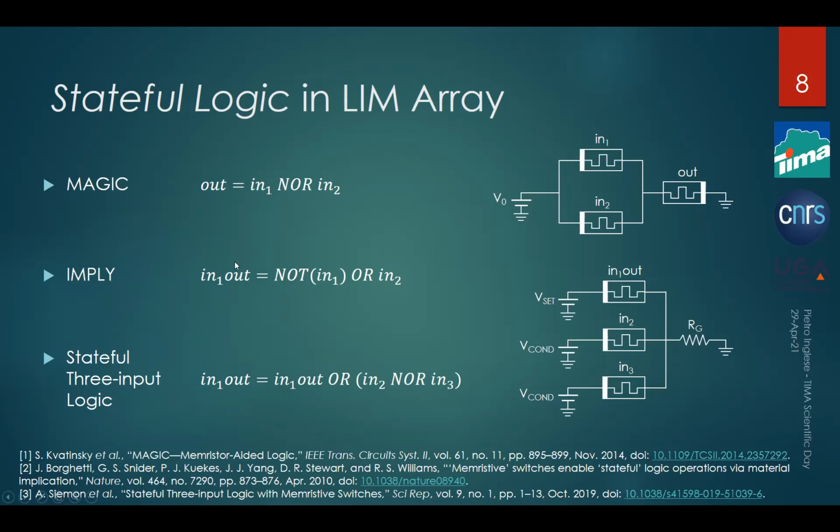While the IMPLY performs the implication logic, the stateful two-input logic performs the so-called OR-NOR, meaning that it performs the NOR between 2 inputs, and finally it ORs it with the third input.